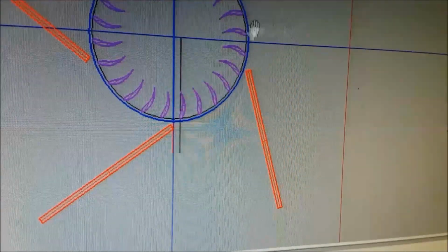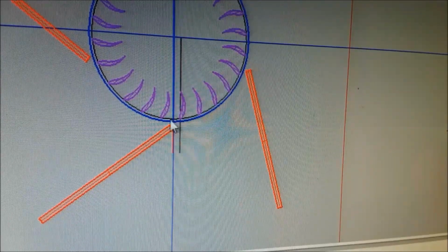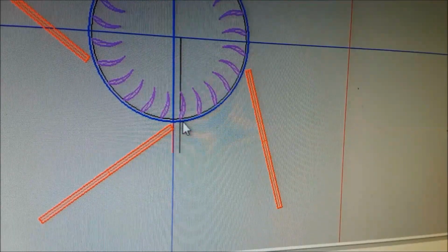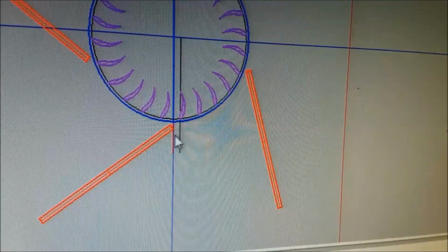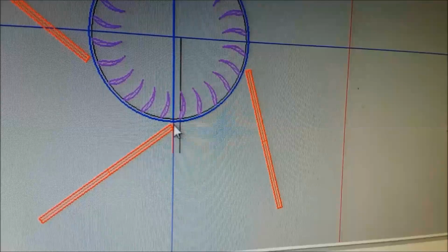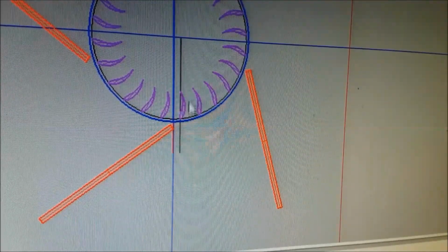Okay, now we're both looking at it. All the air that slides down this thing here, you'll notice that it's seeing about a 20-degree angle of attack. The angle between this and that's about 35, but this thing it's going to hook some. The air's going to redirect a little bit coming off that edge, about 7 degrees. So this is making lift.